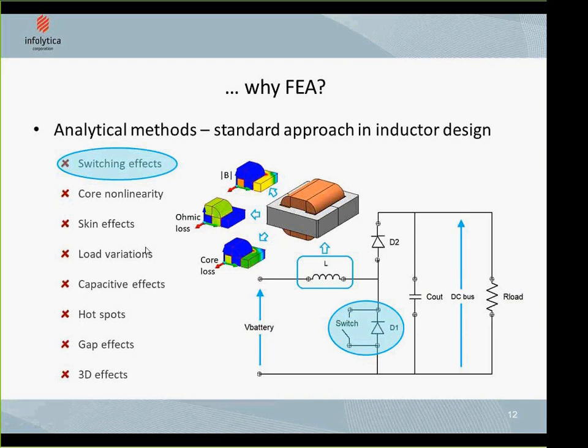So what I said before, the advantage of the control switches is you can use any voltage to control the switching transitions, which allows you to give feedback, or you can use the current through any of these elements to control your switching transitions. And we are going to see how we can actually do this for a boost converter that you can employ in an electric vehicle drive.